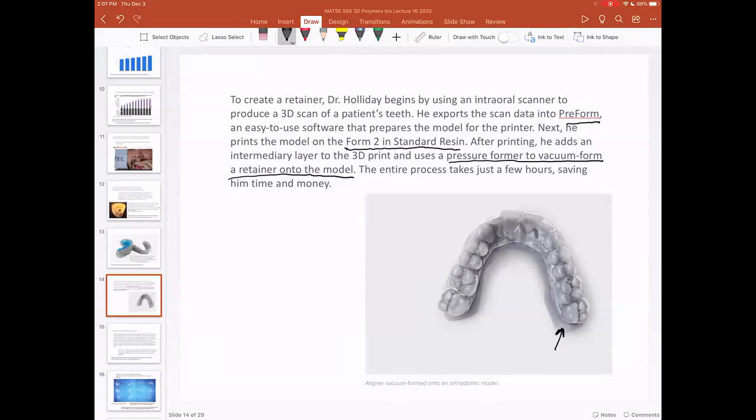And so we talked about this before, where instead of 3D printing the package that you need, or 3D printing the component that you're going to sell, you 3D print a mold and then use vacuum forming or another type of high-speed manufacturing in order to get the component you want. Just like the customized chocolates from Hershey, they're not going to cast chocolate in a 3D printed mold, but they'll 3D print a mold and then use vacuum forming to vacuum form food grade material over that mold so that then they can cast their chocolate in a food grade mold.